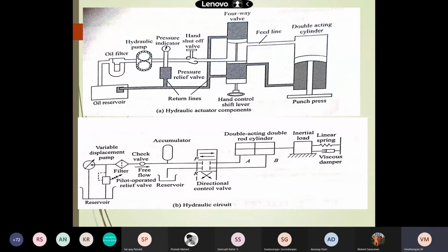The pumps may be classified into various types, either as a hydrodynamic system or a hydrostatic system. The hydrodynamic, or non-positive displacement pump, and the other one is the hydrostatic, or positive displacement pump. Here a pump is given, the spur gear pump, and that is classified under hydrostatic or positive displacement pumps. In that we have the gear pump, vane pump, and piston pump.